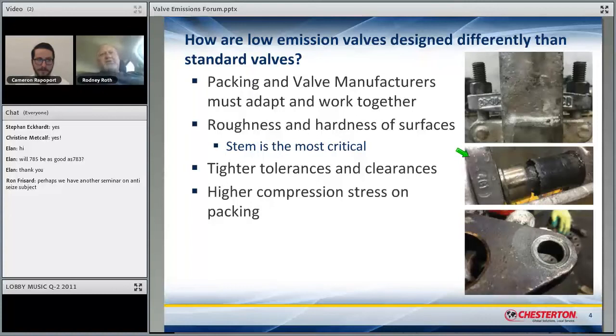However, the standard says that the stem can be under tolerance a maximum of 14 thousandths, but requires a bore over tolerance, which we call the Y factor, of 15 thousandths. So if you made your stem to the minimum and you made your bore to the maximum, which is required, that combined difference is 29 thousandths. That's 29 thousandths of tolerance.